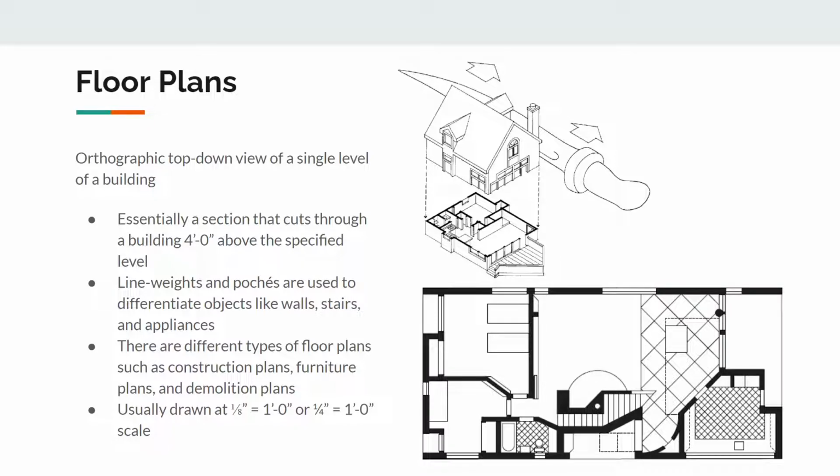So you would have all of your areas of the floor plan with their own respective notes saying, for instance, what the flooring finish is going to be, what the wall finish is going to be, what the paint color is, or whatever you're putting on. Is it a wall covering? Is it just paint? Are you doing tile on the wall? All of that, base finish, ceiling finish, is going to be represented on the finish plan.